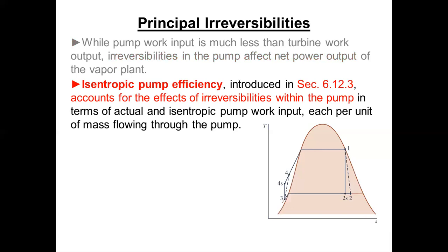And of course, in the ideal cycle, we say we would just come out at 1815 psia or 1800 psig, and we have no pressure losses. But in the real cycle, we probably have to come out 200 to 400 psi greater in order to move everything through the boiler and get the steam out into the system.